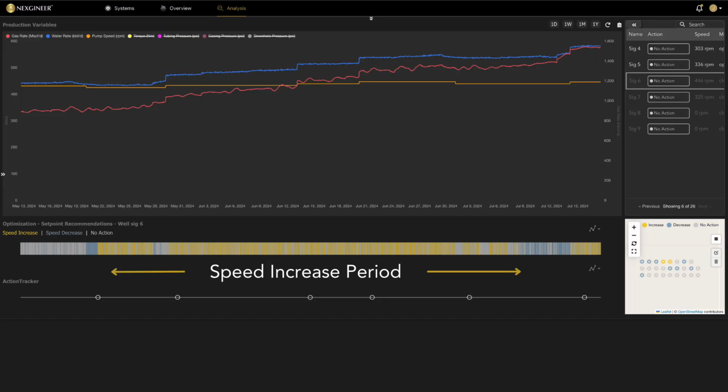So what is the difference between the manual engineering operation and the smart controller supervision? The manual set point adjustments are made at a slower rate compared with the recommendations from the smart controller. The smart controller generates recommendations that capitalize on the positive adjustments in water and gas rates, while remaining conservative when there are dynamic changes in the system that can increase the risk of failure. This series of smart controller recommendations demonstrates an example of where production could have been accelerated, all while considering the constraints we impose on the system.